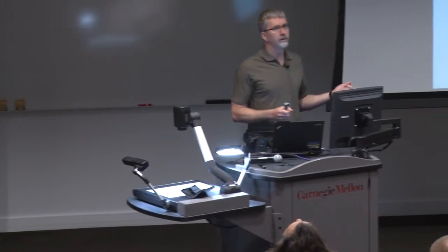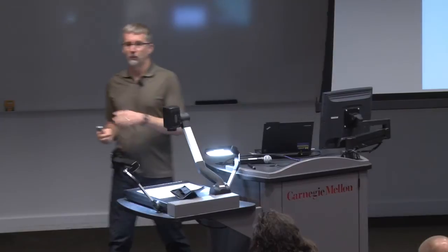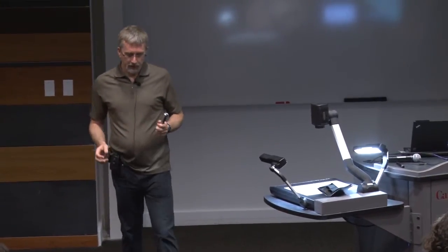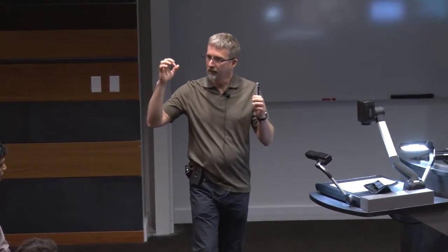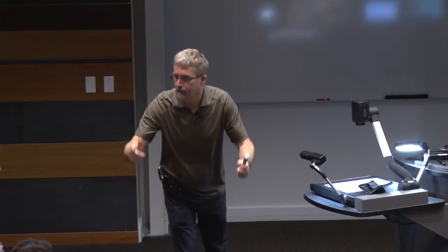We have problems with yaw when we have really, really bad foot placement. So we had 8 reasons for having swing leg retraction. Let me add a 9th one. If you're walking and you scuff like this, huge yaw. If you come forward and you still haven't done your leg retraction, but this leg is trying to come back and this one is going forward, you don't have yaw. That's the 9th reason to do swing leg retraction.